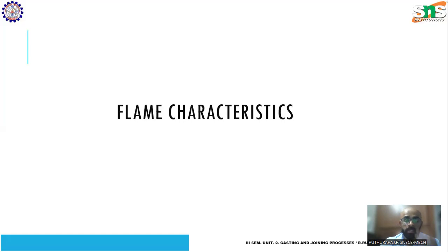For example, if acetylene is higher and oxygen is lower, you will get carburizing flame. If oxygen is higher and acetylene is lower, then you will get oxidizing flame. If both are in the same volume, then you will get neutral flame. So what the name indicates, we will discuss. First, we will discuss the